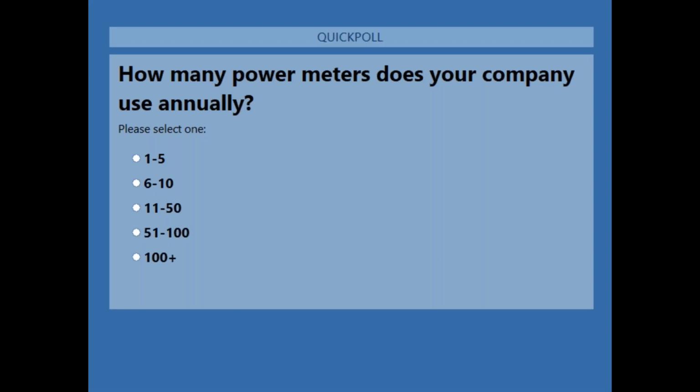We have specifications for both our split core and Rogowski CTs on our website, and those data sheets show the output signal for those. As long as the CTs that you're using on the job site are compatible with the same signaling output, then those CTs can be used as user-defined in the configuration of the power meter itself.